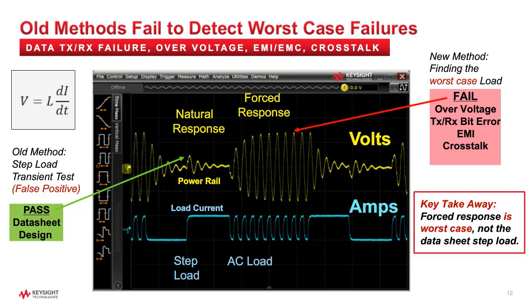Normal operation of the load may never excite this resonant frequency, but digital systems are very wideband, and it is hard to test all combinations of operating scenarios. For example, power-saving modes that turn on and off and bursted data can easily create high-speed digital load transients that extend from kilohertz to gigahertz.